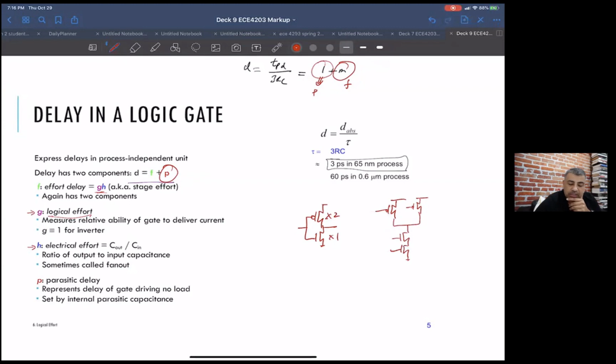So what I'd like to do is size this NAND gate to have the same drive, the same equivalent current output or the same equivalent resistance as this inverter. Can you help me size these devices? Basically we want to make this pull down resistance the same as this pull down resistance. What do you think we should make the size of these two devices?